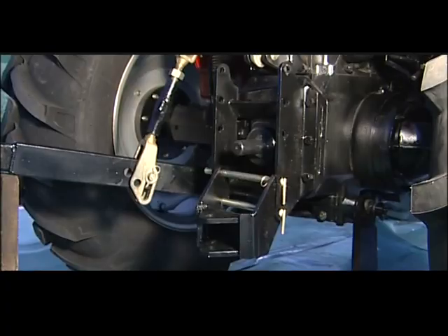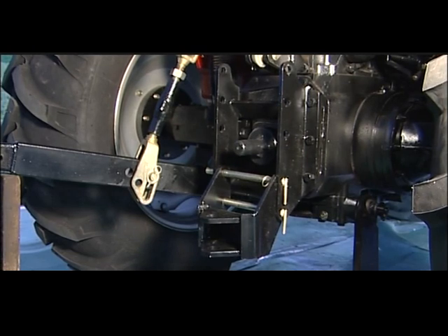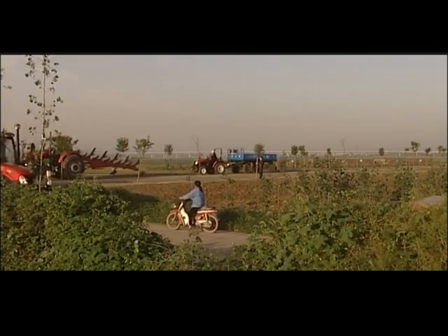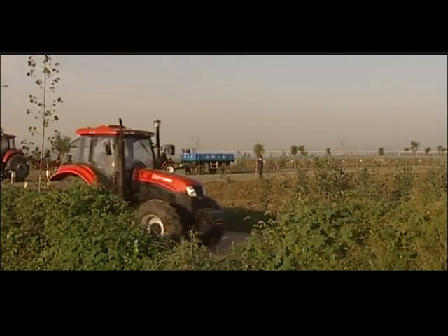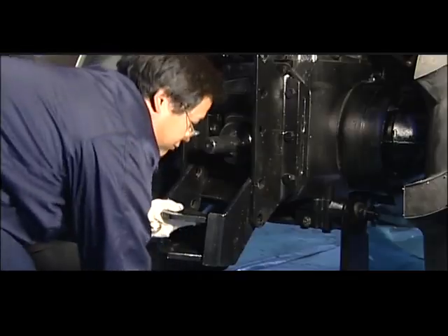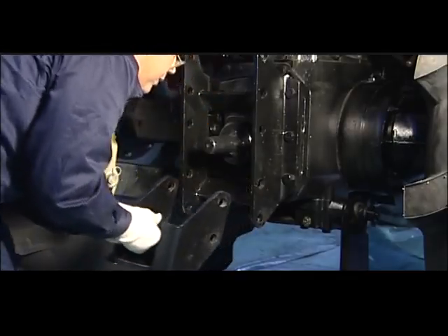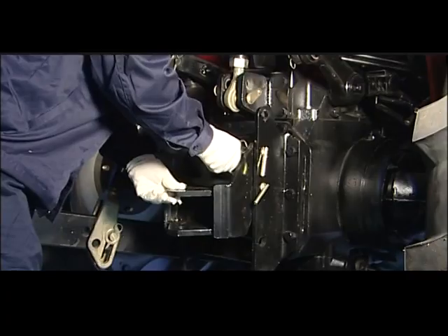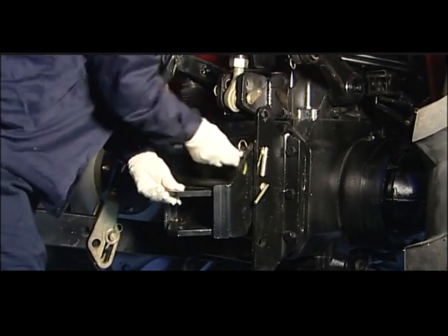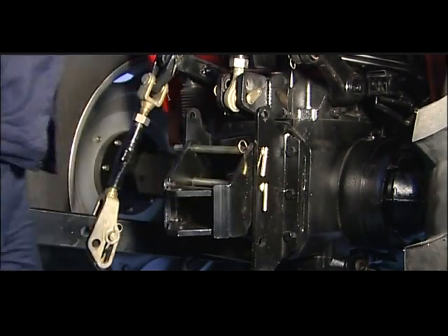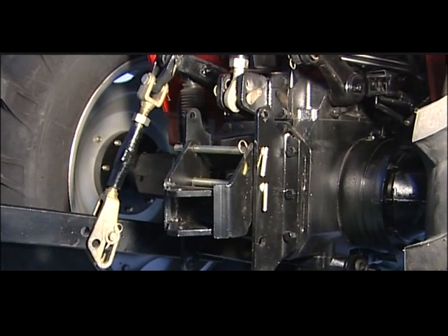Usage of drawbar hook with hitch device. Choose the drawbar hook and hitch device based on the types of implement and trailer and local rules and regulations. The correct selection of drawbar hook and hitch device will deeply influence the operation performance and the stability of the tractor. The adjustable drawbar hook is suitable for all types of trailers. There are 6 adjusting locations to be chosen.